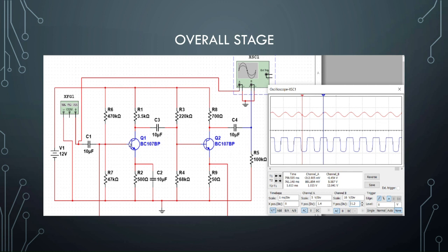The first transistor amplified the value, but the value became negative, and then the output at transistor 1 becomes the input at transistor 2 and is amplified again, but inverts the value into positive. So we get the sinusoidal signal right here. So beautiful.